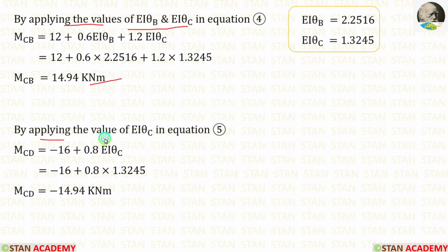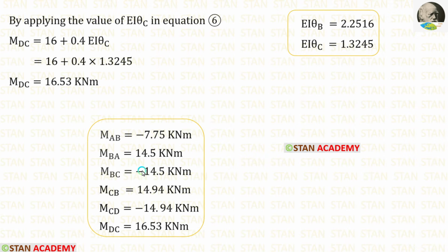After applying the value of Ea theta c in equation number 5, we are getting MCD. After applying the value of Ea theta c in equation number 6, we are getting MDC. In this analysis, we have calculated all of the moments.